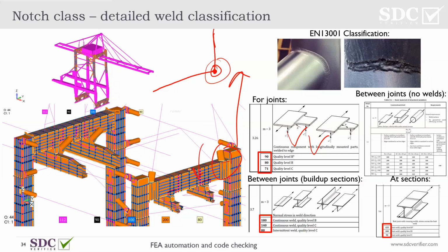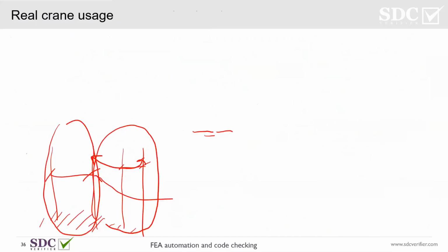That's a good point. Although most engineers simply use a general approach. For example, if I have the shell model with nodes like this, they simply extract elemental stresses from the intersected elements, which is pretty much okay, because if you put the thickness on, you see that if you extract at the distance of half of your plate thickness of an element, then it's still a good representation.